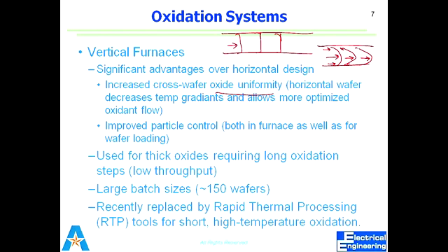So when the lower half of the wafer is at high temperature, the upper half of the wafer is not at that temperature initially. It means that the lower part gets more silicon dioxide, a higher oxidation rate, compared to the upper part. So the overall profile of the wafer will not be uniform. You won't have a uniform oxide layer on the wafer surface due to the non-uniform distribution of heat.